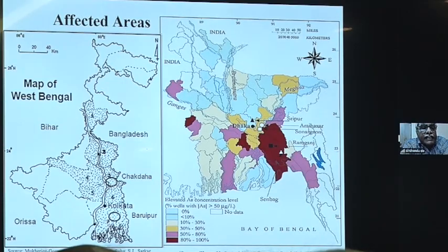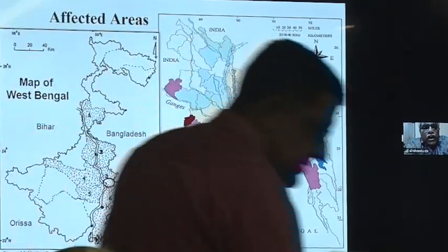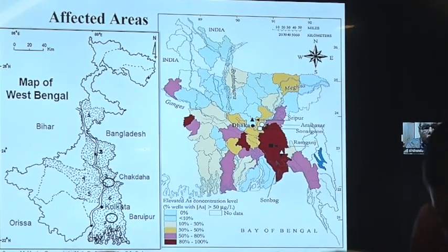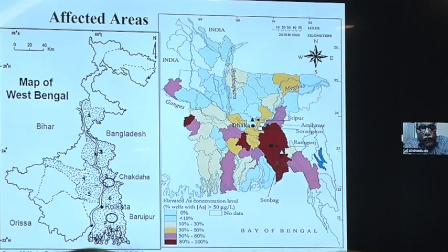We found out the lateritic soil contains lots of iron and aluminum hydroxides and oxides. These aluminum and iron hydroxides are strong adsorbents of arsenic. So they absorb arsenic and they do not release it. Therefore, arsenic does not get released from the rocks in the soil, and it will not be released into the groundwater, preventing the contamination of the groundwater in these districts.